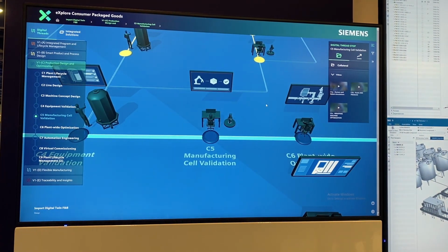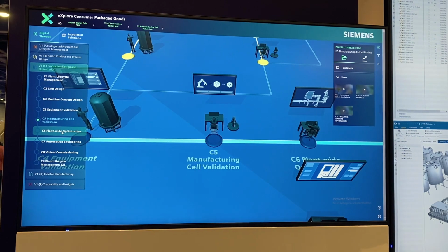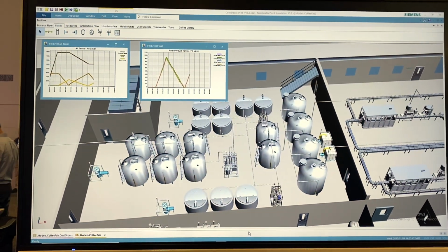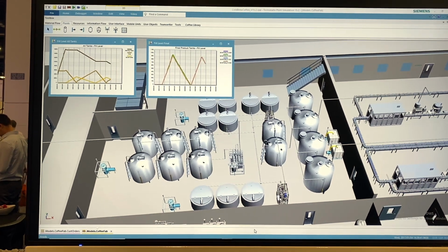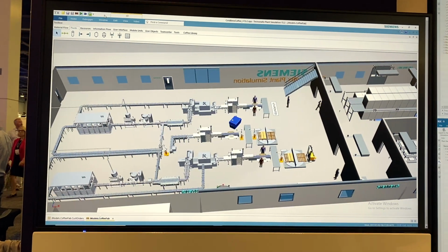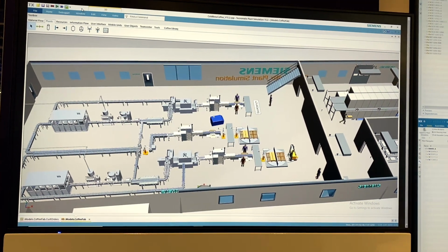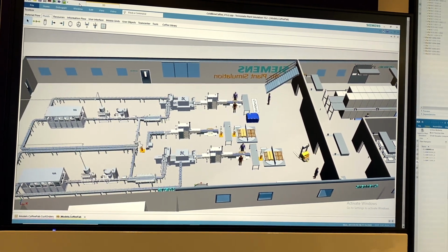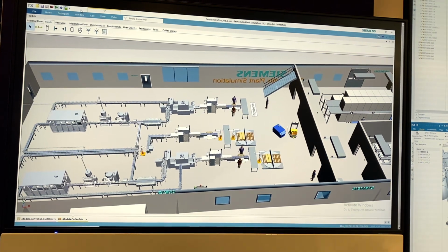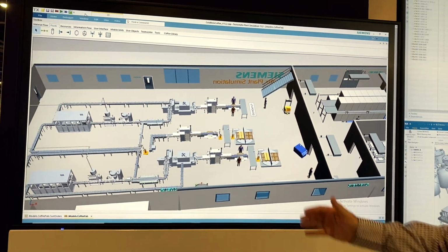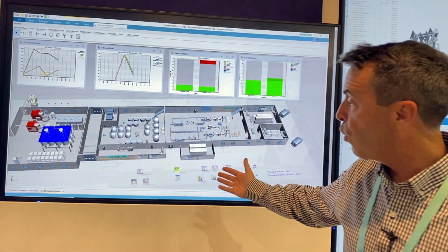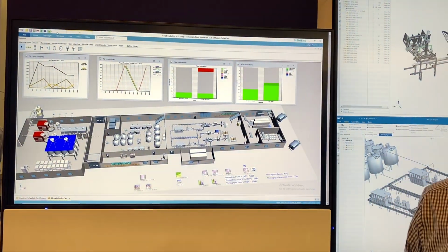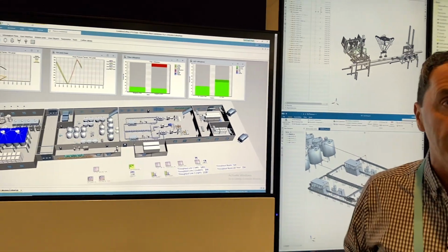And we're doing that to help ensure the layout, and ultimately, if we move down the line from a manufacturing standpoint, if we look at our plant-wide optimization, we want to verify, is our facility giving us the output that we really want? What are the statistical analysis bottlenecks, throughput time, machine efficiency, labor efficiency? Am I producing what I need when I want it? Do I need extra equipment, extra buffer lines? So we can simulate this all ahead of time before anything is built.